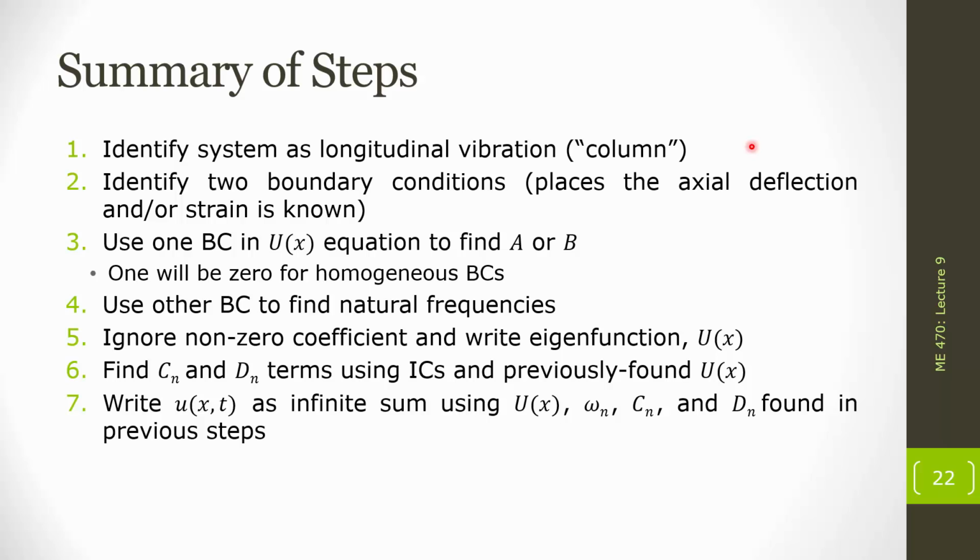And do we meet the criteria to have that partial differential equation from the previous slide? Are we operating only in the linear elastic region? Are we not buckling our column? Do we have free vibration? Is the cross-section constant? Are the material properties constant along the length and also in terms of time?